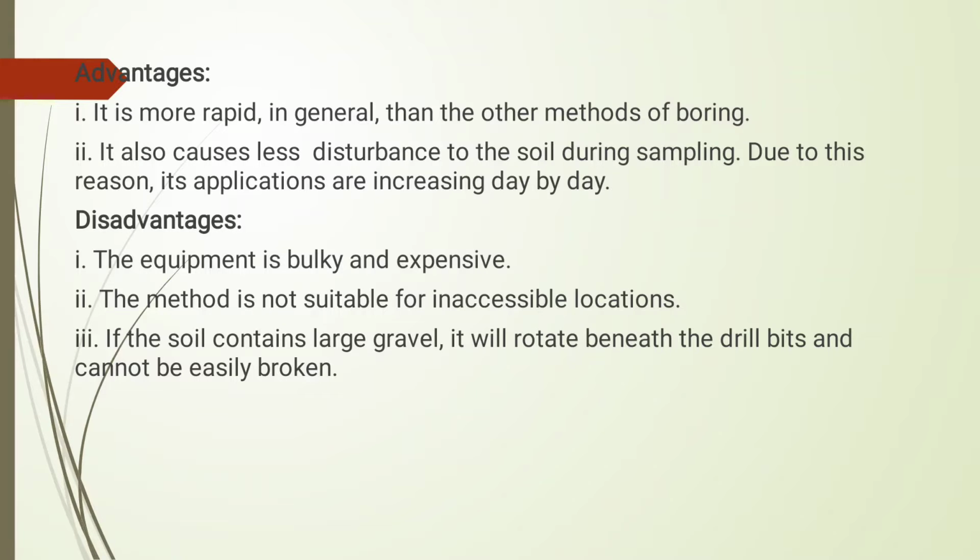It is more rapid than other methods. It also causes less disturbance to the soil during sampling, and for this reason its applications are increasing day by day. Disadvantage: the equipment is expensive and this method is not suitable for inaccessible locations. If the soil contains large gravel, it rotates beneath the drilling bit and cannot be easily broken.